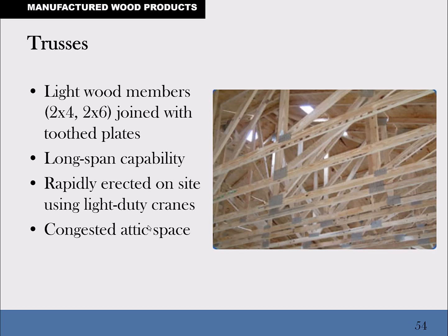But in an area that has any significant snow loads over a 100-year period, and some areas that don't get snow too often still have to follow this, you have to have your roof engineered, which means typically you're going to do that with trusses, most likely. The building inspector won't sign off on it in those areas, so you'd have to have an engineer sign off on the roof one way or the other. And it's more affordable when you buy trusses because they come with the engineering built in. As long as you install it per the manufacturer's instructions, the engineering came with the trusses.